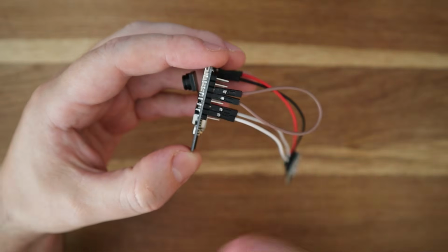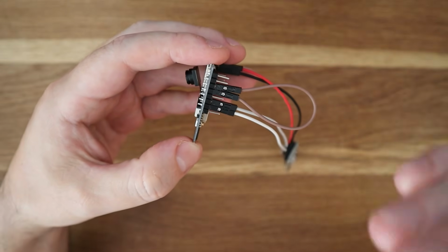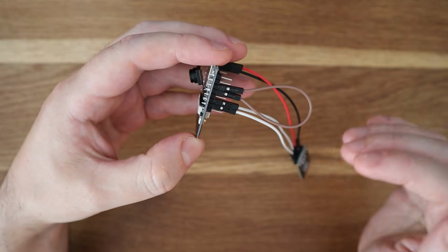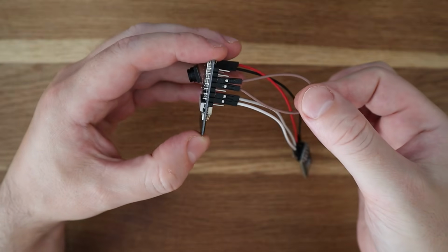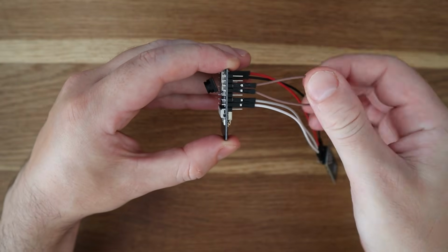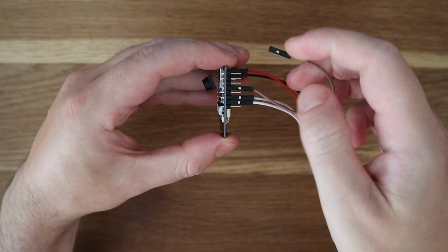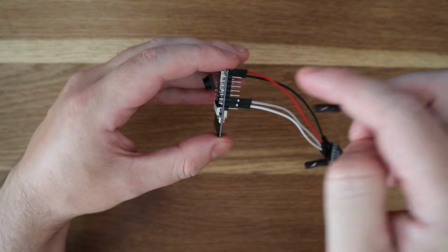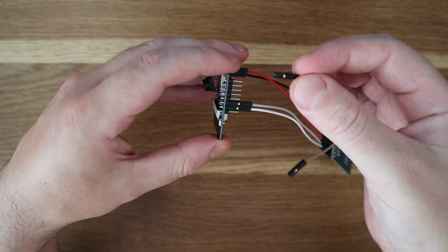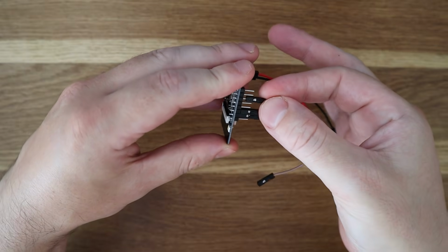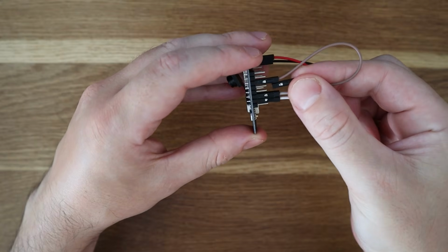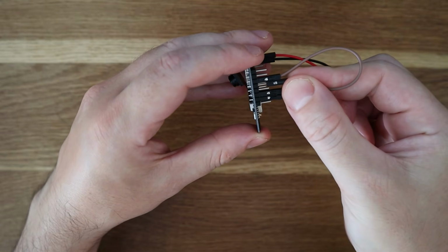Once we have already uploaded the code and once we are ready to execute the code in the ESP32, then we are going to remove this connection over here. Remember what I told you, that this one over here is only for telling the ESP32 in what state it is currently in, right? But let's take it one step at a time. So for now, I'm just going to connect it like this.